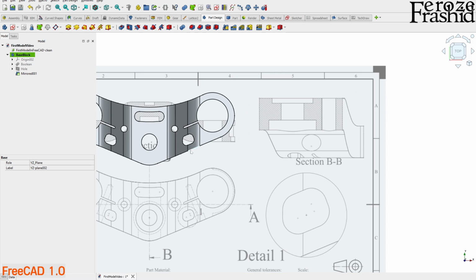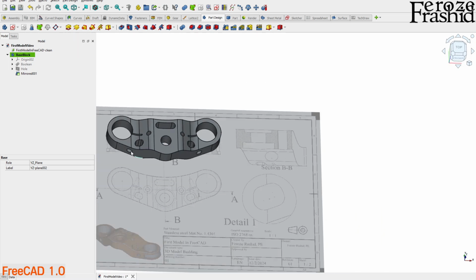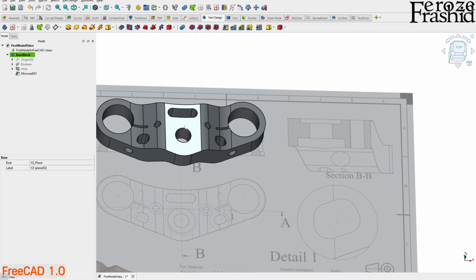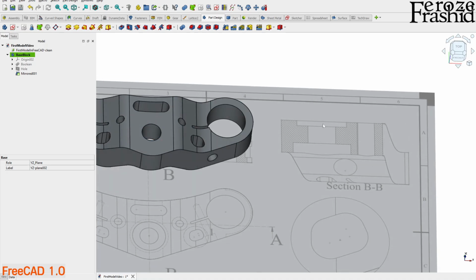When I started building this model, I thought of making it a hole, just like what we did, so we could have the counterboring there. But because we have two counterborings in there, I wanted to make it separately. So I plan to make a revolved cut, a groove, to have both cuts done at the same time.